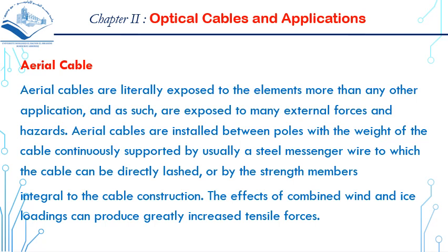Aerial cables are installed between poles, with the weight of the cable continuously supported by usually a steel messenger, to which the cable can be directly lashed, or by the strength member integral to the cable construction. The effects of combined wind and ice loadings can produce greatly increased tensile forces.